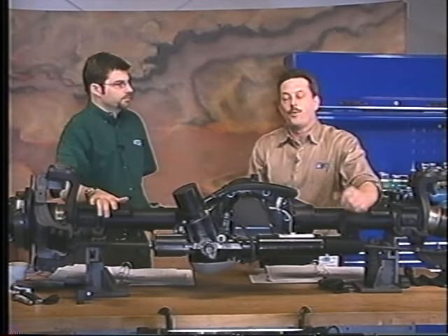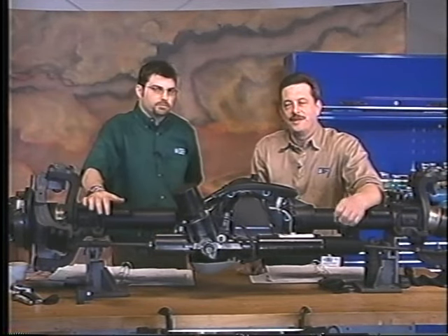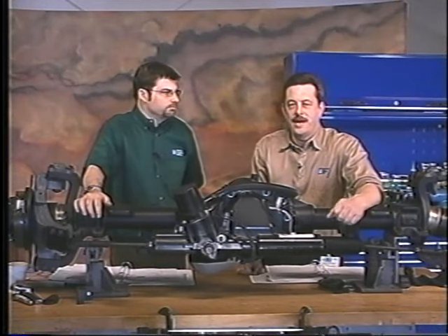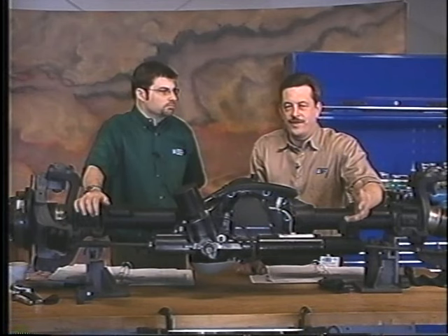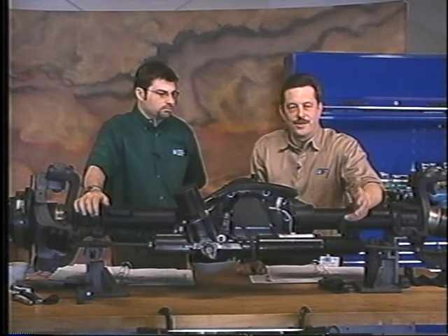All right. Now, a couple of quick tips about the system. Think about this. GM recommends you do not use tire chains on this vehicle. Makes sense, because when you put tire chains on, what do you do? You increase the width of the tire, you increase the height of the tire. Now, start turning it, what's going to happen? Well, there's the possibility of making contact with the wheel housing. That's obviously going to cause some damage. So GM says don't do it.